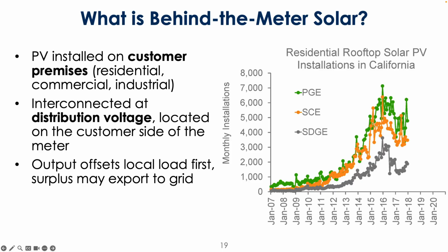Just to check my understanding of behind the meter solar: if the PV system is at that time only serving the load of the house, it is not increasing the voltage of the distribution network, right? Yeah, that's right. But when it exceeds that, that's when the network gets a little extra loaded, if your batteries are full. If you're exporting it to the grid, basically. Yes, exactly.